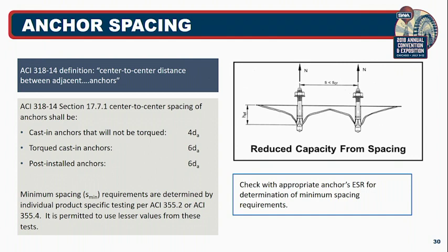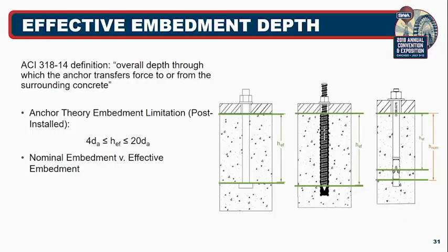And note, if you're designing with mechanical anchor systems, sometimes they do offer different cases as well, depending on the spacing and edge distance. So for the anchor spacing, if it's fairly close to the edge, right, the minimum anchor spacing might be a little bit more than if it's further away from the edge, where there's not that edge distance reduction factor to take into account.